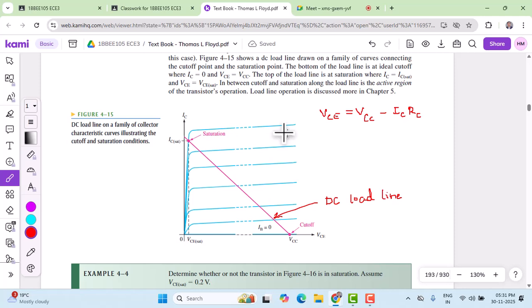That is within our existing conditions, VC max. Now whatever the defined value, let us calculate the product and check whether that product of VC max and IC exceeds our power dissipation of 800 milliwatt. So VC max is 15 volts and IC is going to be 19.5 milliampere. That gives us 293 milliwatt, but the PD max is going to be 800 milliwatt. So the power dissipation 293 milliwatt has not exceeded the 800 milliwatt.